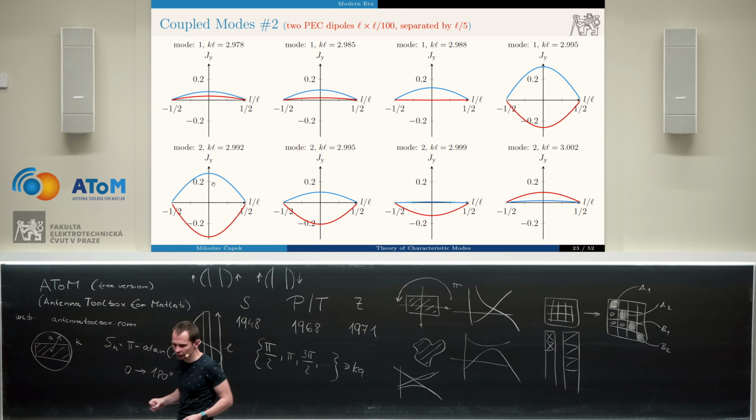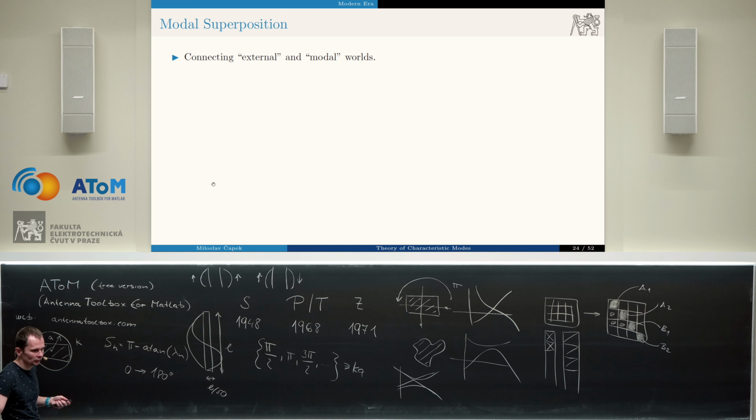So this is really a problem of tracking, and it's telling us actually a very important conclusion, that tracking is or should be not important for us. It's not important how the modes are connected at different frequencies, because we live in the frequency domain. And at the end of the day, we will sum up all the modes together.